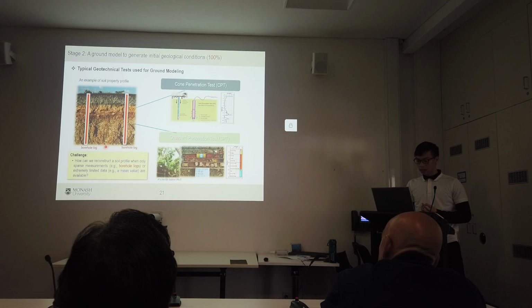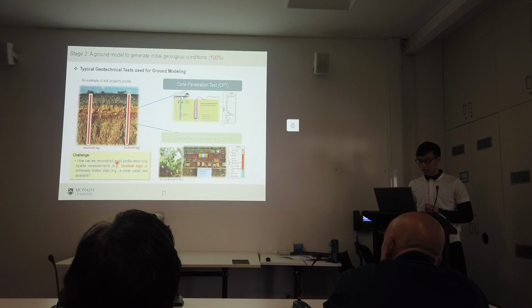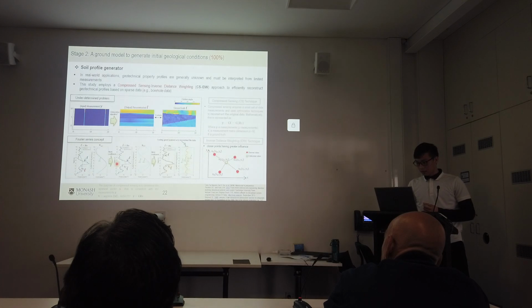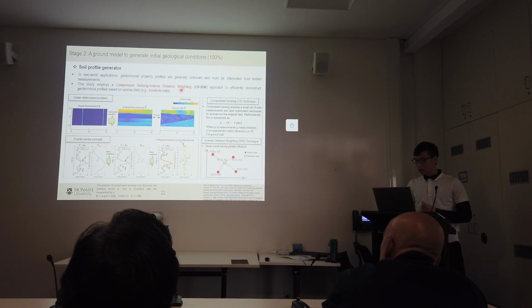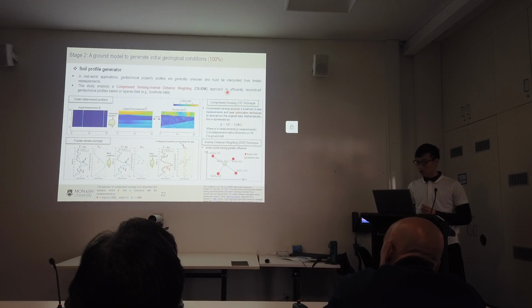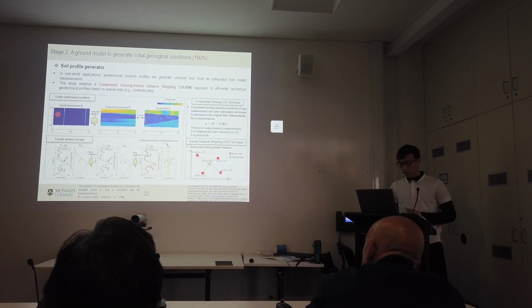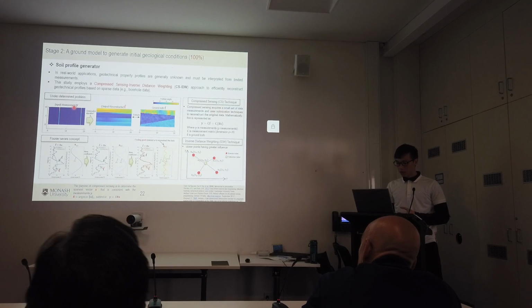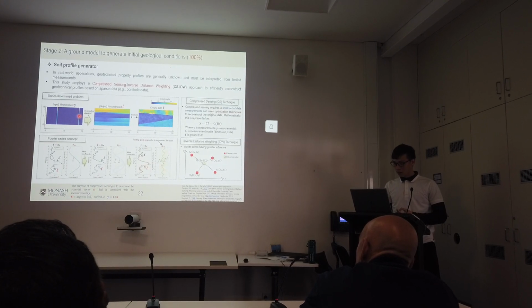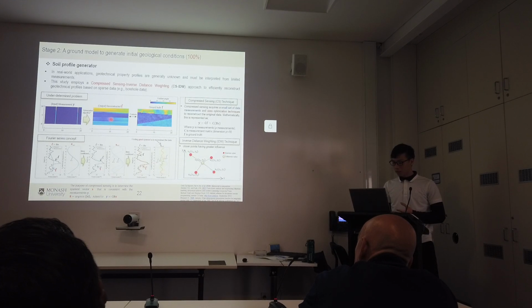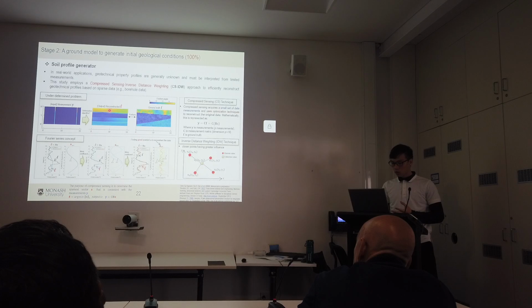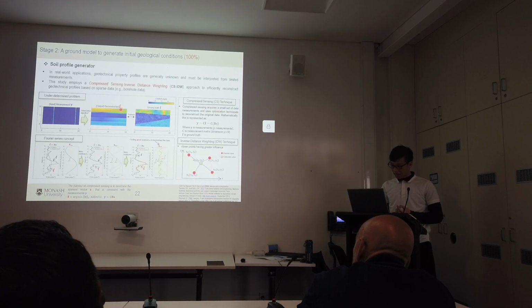Here we want to highlight the challenge. If only limited data are available, how can we reconstruct the entire soil profile? In my research, we use compressed sensing and the inverse distance weighting technique to reconstruct the entire soil profile. So first, let's look at this picture. Assume that we have the input measurement y, which is the borehole data. The output that we want is the entire soil profile, which we call the reconstruction f hat.